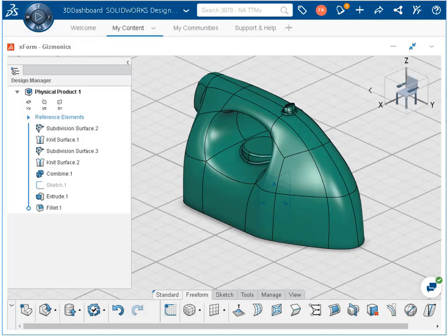The sub-D surfaces can be reshaped by manually changing the topology, by pushing, pulling, dragging, or rotating elements of the surface. In addition, there are many shaping tools that can be applied directly to the topology. After editing, the sub-D surface is automatically refined to create a smooth curvature continuous, or G2, surface. These surfaces are eventually converted to NURB, or non-uniform rational B-spline surfaces, so that they can be used with XDesign and SolidWorks.